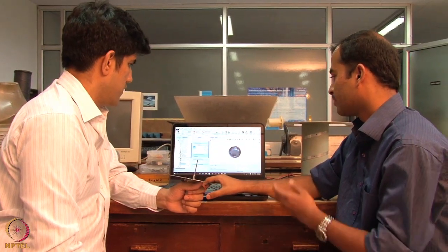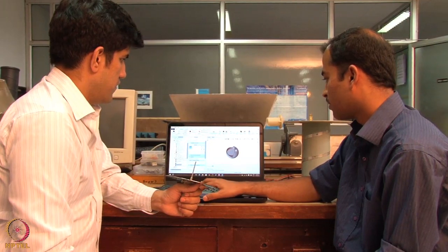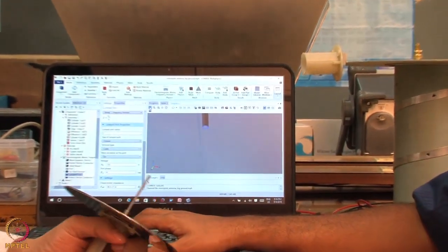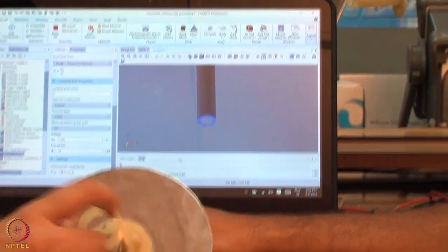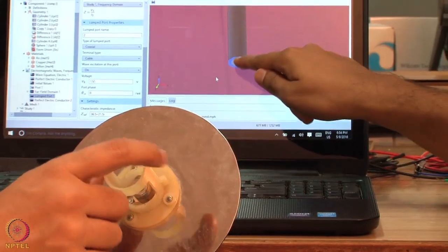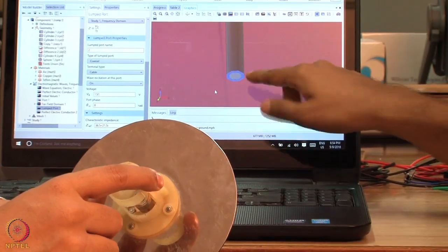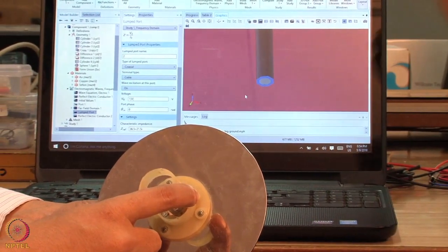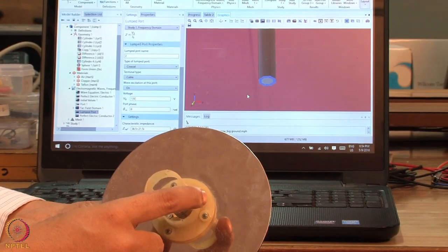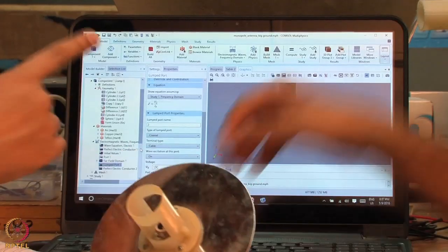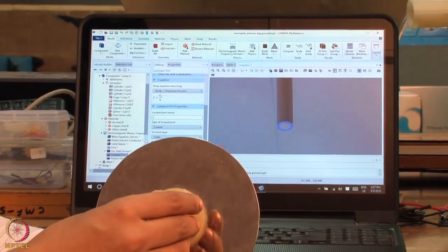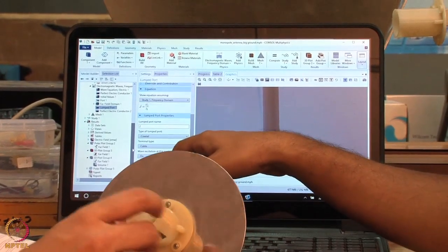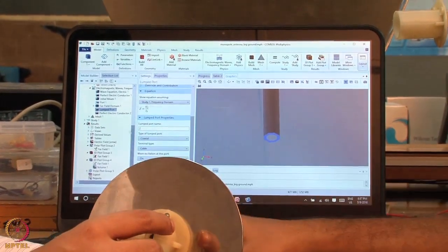Now the feed here is the coaxial port, the lumped port. This is the part where we have the coaxial feed coming in. This is the inner conductor, and that is the outer conductor, and between them is the Teflon. We have just given the excitation to that part, so the signal will travel in that part. So we have given the coaxial feed to this part itself, we have excited it with wave excitation, and this port is on.